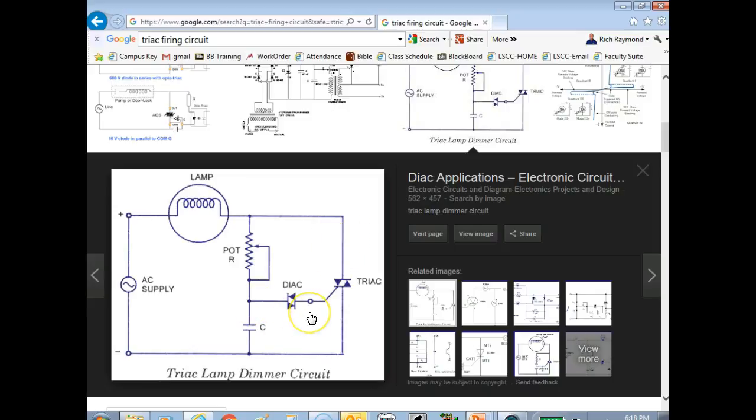If you've got a light that comes on at night, or a motion detector that only comes on at night, and the light stays on all the time, usually it means that your triac is shorted. If you can get in there, get the part number on it. If you can't get the part number, you can get the ratings on the thing, 120 volts, so much current. If you're running a 100-watt bulb, you can pretty much figure out what triac to put in there.